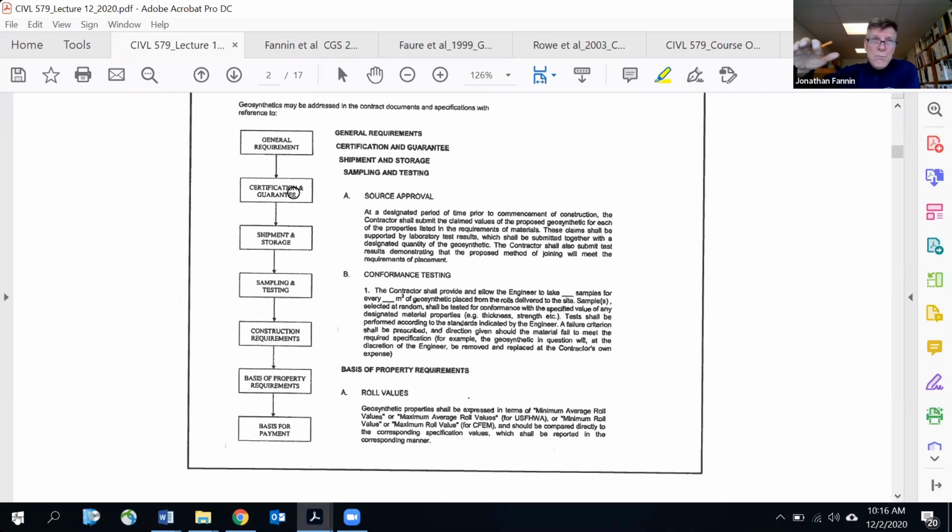The materials were excess to the previous year's construction season, and they were going to be used again. And the comment was, we will strip off the outer portion of the roll of the geotextile because we know it will degrade in UV light over the course of the winter. And recognize that, and so you'll write requirements for storage.